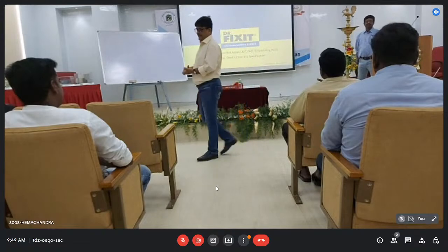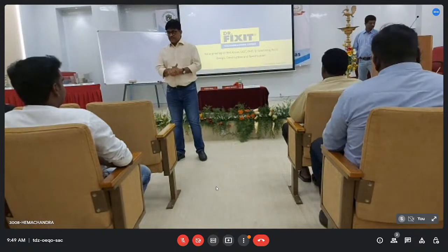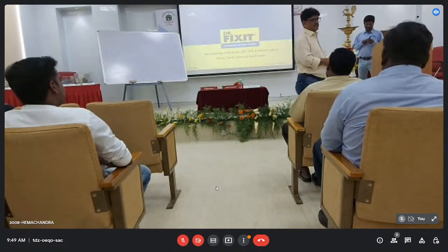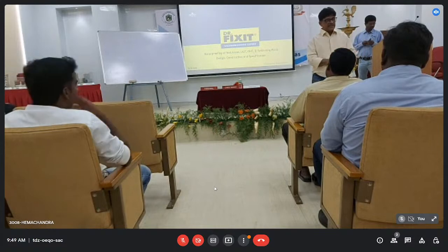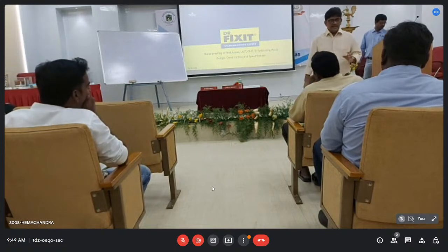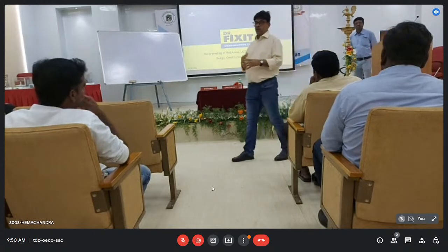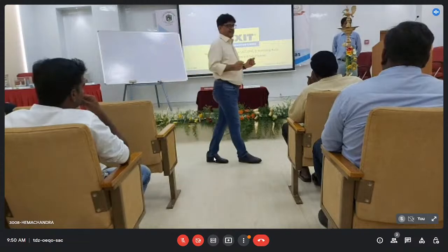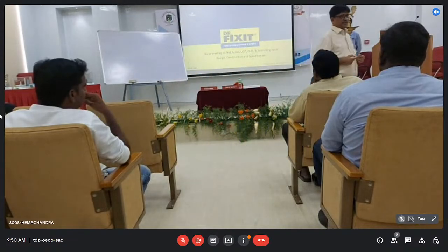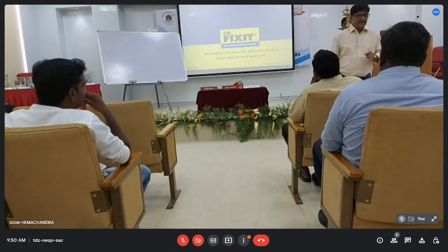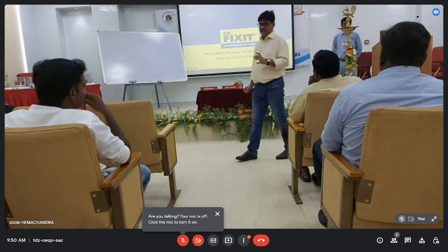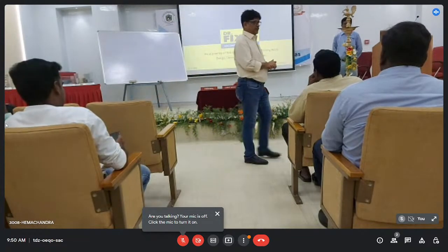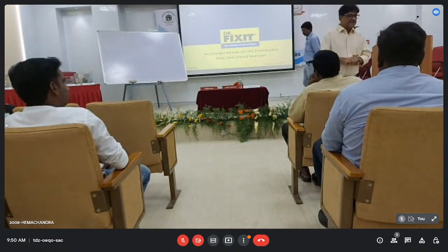And the second session we took was the basement session: the foundation, substructures, and the basements. So different areas of the basements, what are the grades of the basement, what are the types of waterproofing, and what kind of waterproofing is to be selected for what, where, and why. Right? That is most important, why it is to be selected. The materials and the systems are not that important. It's important why you have selected the material and how I should execute that in the right manner so that it works. So we talked about the designs, drawings, how to do the basement waterproofing. Am I right, everybody? Clear on that?